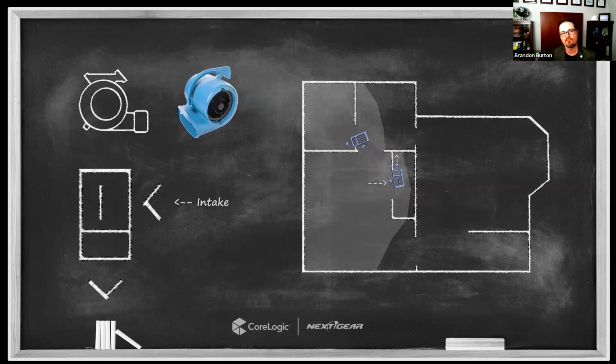Because of how these air movers are designed, if you're standing above the air mover, taking a look at it, that intake is only on that right-hand side that you see on the screen, all right? And the exhaust down at the bottom. That's where the intake is, regardless of manufacturer. It doesn't matter who made the air mover. They're all the same. That intake is on that same side and the outlet is always in the front. So the only way to make this exchange work across all these openings between adjoining rooms, believe it or not, is to install them in a clockwise orientation.